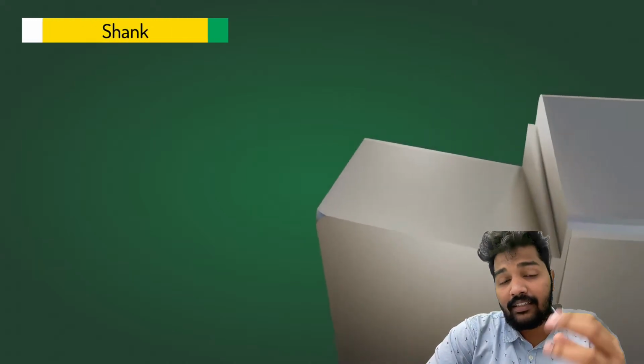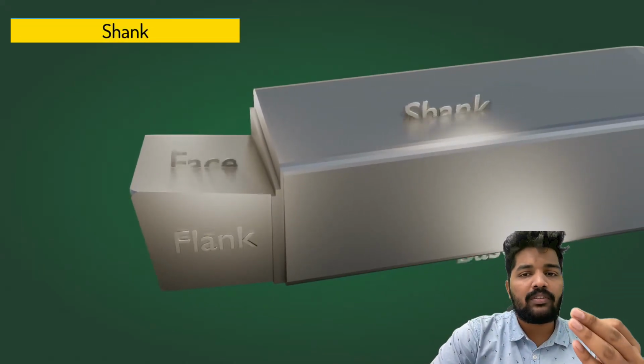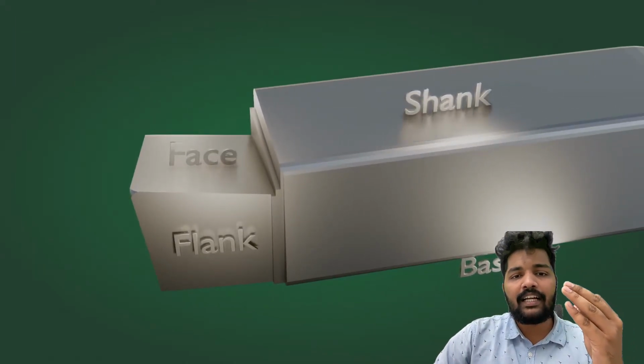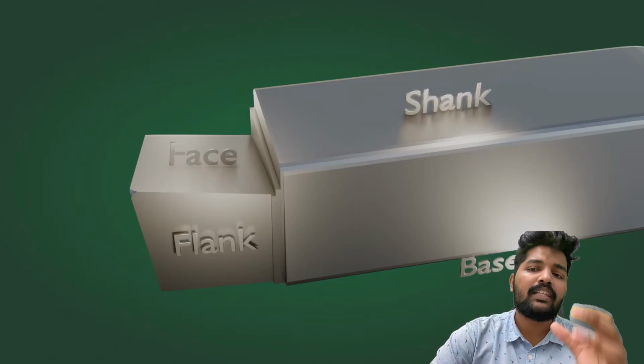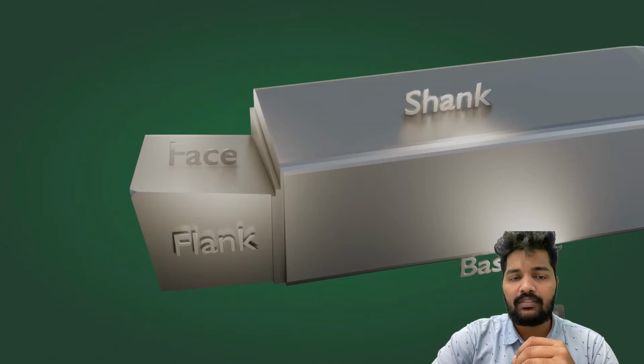Fourth, we have the shank. The shank is the main body of the tool, acting as a support and holder for the entire tool. It is clamped into the tool holder, securing the cutting tool in place during machining operations.